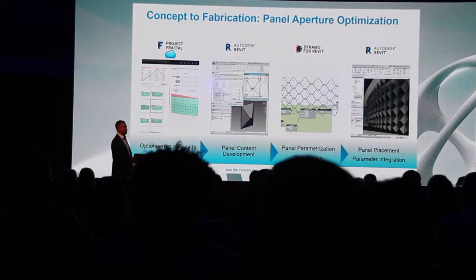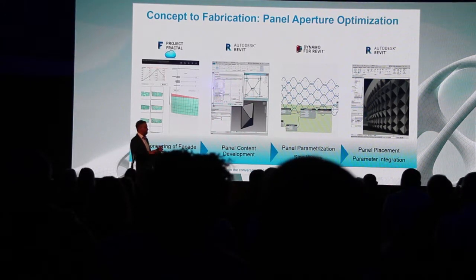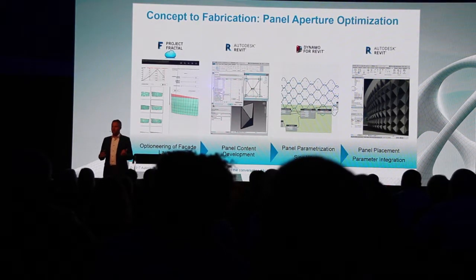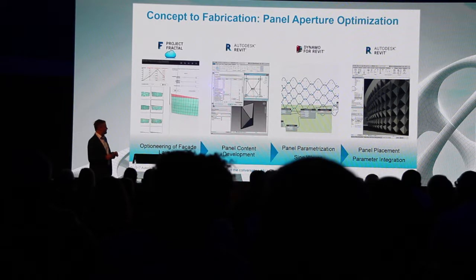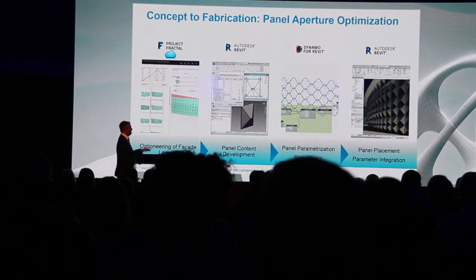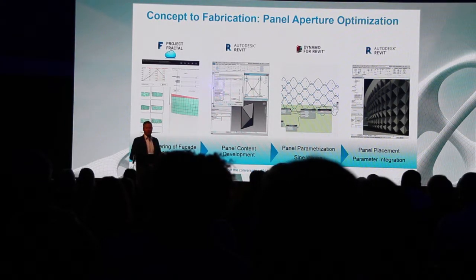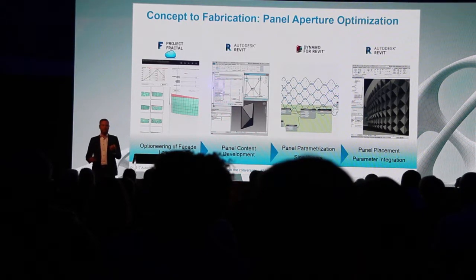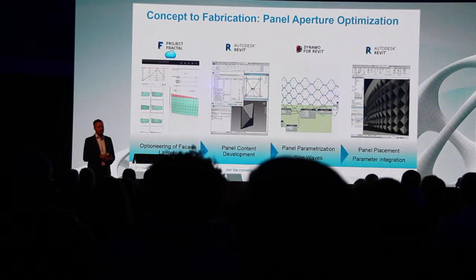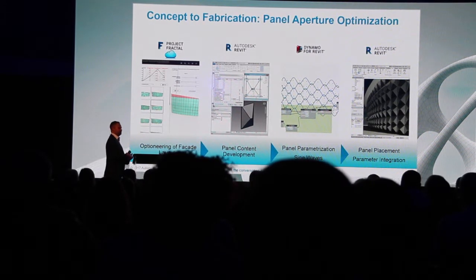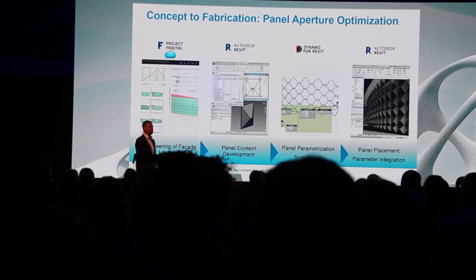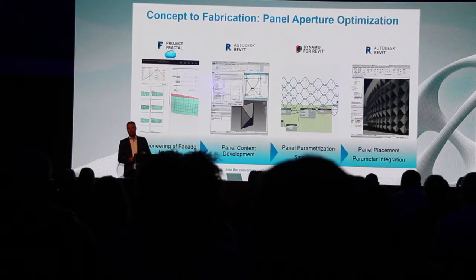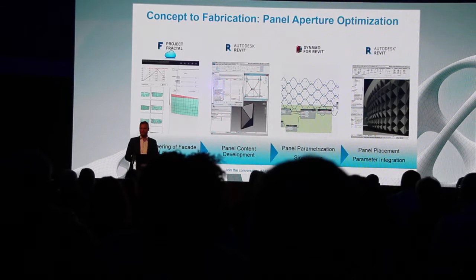And Schuko have a very nice parametric system for facade panels, which is based on tripods. Tripods that are connecting the tubes in each corner, and these tubes have like a custom length. The tripods are like fixed elements with some holes in it. Now if we use these fixed elements, if we use these boundaries as internal angle calculators, for instance, then we can find an optimal solution for it.